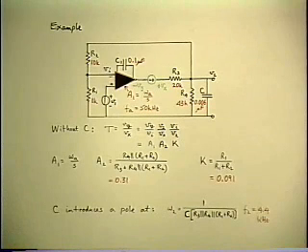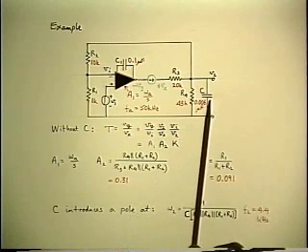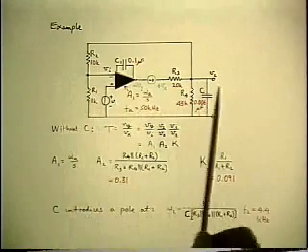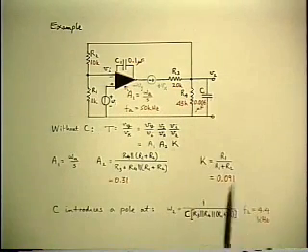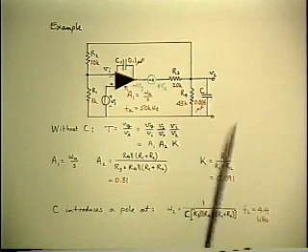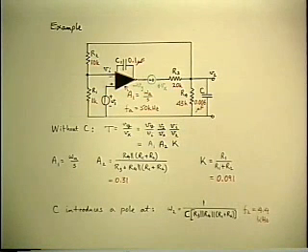And once again, we can anticipate a shortcut method. There's a capacitor out here that's going to cause some corner frequencies, and it's part of a couple of dividers. So the easy way to do it is to leave the capacitor out, find the mid-band value, and then put the capacitor in using the extra element theorem.